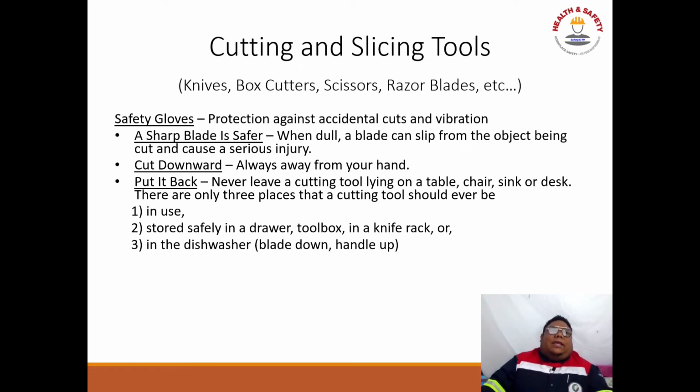Be proactive always if you are in safety. Second, cut downward, always away from your hand. That's why there's a procedure, guys: if you are cutting a cable, do not cut toward yourself, cut away from your body. And put the tool back. Never leave cutting tools lying on a table, chair, sink, or desk.